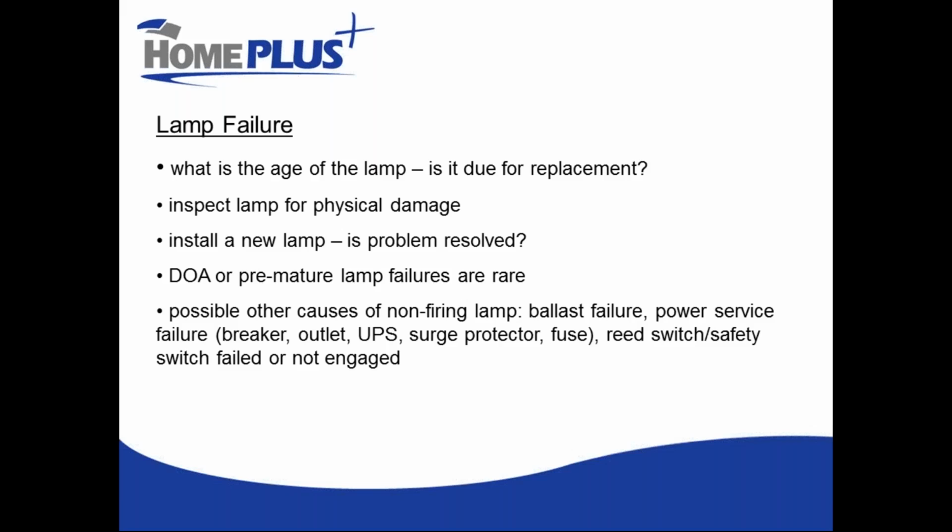So that could be why you're getting those recommendations, is in order to achieve those other objectives, you have to. Now, I would certainly say if those factors are not in play, you're not having problems creating residual at the end of the line, for instance, if you're getting 2 or 3 or 4 parts per million at the end of your line, and you have suitable chlorine contact such that you can achieve your CT level at a lower level, then I would say it would probably make a lot of sense for you to reduce your chlorine.